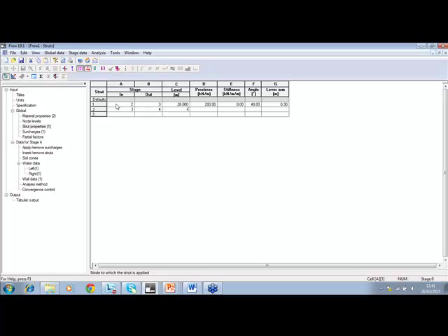So if you look, I've just typed in equals, because instead of typing in 28, if I tab through at the equals, I'm getting the same level and the same pre-stress. But now I need to type in the stiffness because the anchor's been locked, and the same angle, again using equals, and the same lever arm. Okay, so now the different levels or the different slabs come in the final condition.